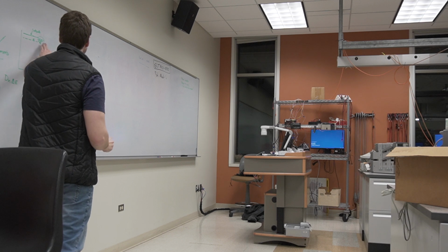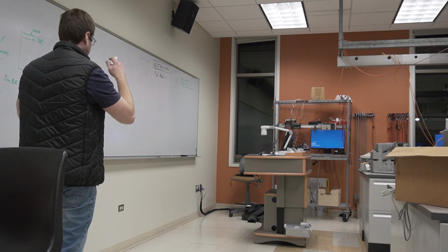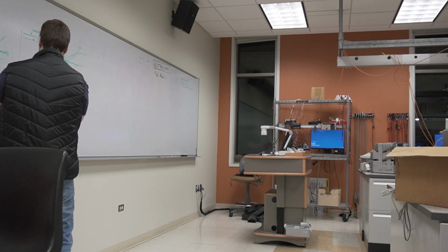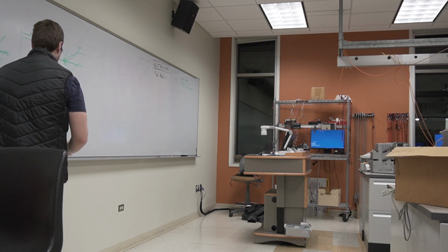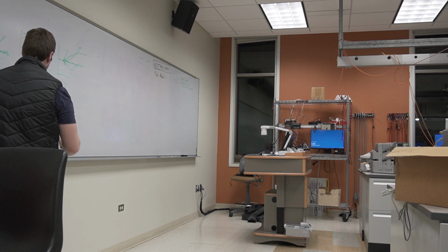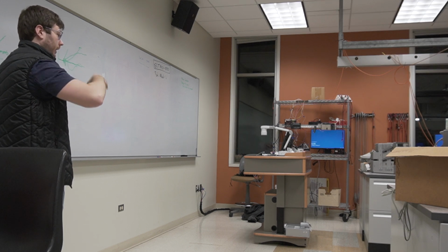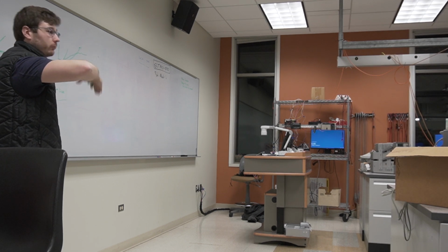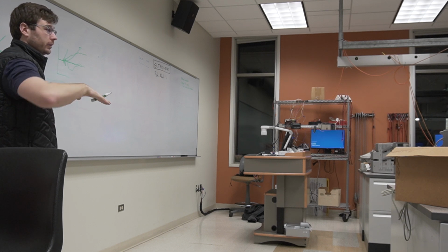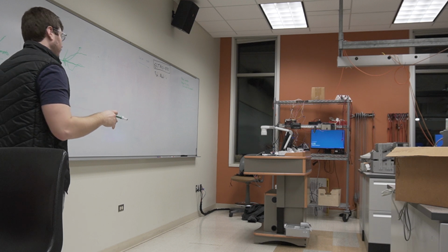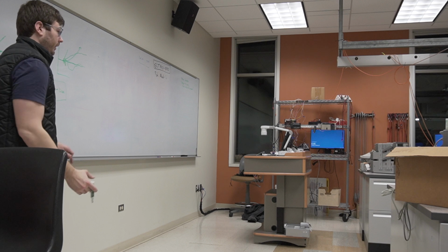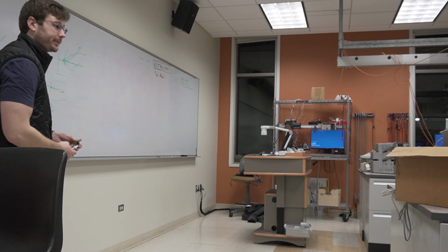And the D is literally the error. At each instant, I'm going to try to fight that error, and the D parameter is how hard it tries to fight. It's D times the error. So if D is really large, at an instantaneous error it'll try really hard to correct. If D is really small, it won't try that hard. It'll see the difference and try to correct it, but the overall performance might be dominated by your P and I variables.